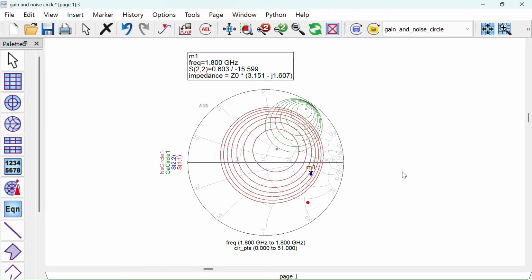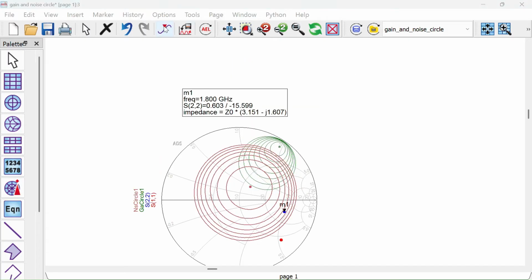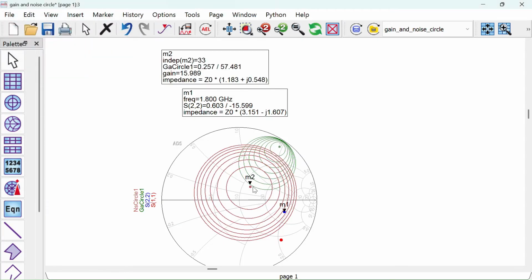Unlike the input impedance, the output matching follows a straightforward approach. The impedance seen from S22 is conjugate matched to 50 ohms, ensuring maximum power transfer. No trade-offs are required for noise figure in the output matching stage.